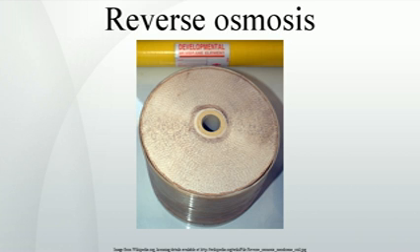Disinfection. Post-treatment consists of preparing the water for distribution after filtration. Reverse osmosis is an effective barrier to pathogens, but post-treatment provides secondary protection against compromised membranes and downstream problems. Disinfection by means of UV lamps, sometimes called germicidal or bactericidal, may be employed to sterilize pathogens which bypass the reverse osmosis process. Chlorination or chloramination, chlorine and ammonia, protects against pathogens which may have lodged in the distribution system downstream, such as from new construction, backwash, compromised pipes, etc.